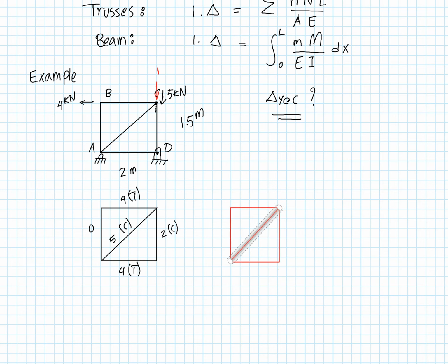There it is. And to really indicate what the forces are inside this structure as a result of the virtually applied external force. And we'll have a force of 1 kilonewton in compression in this member on the right.